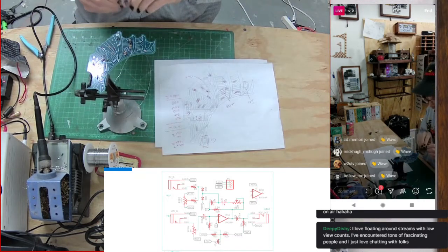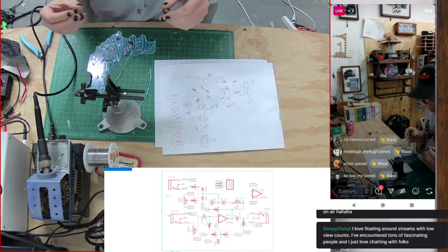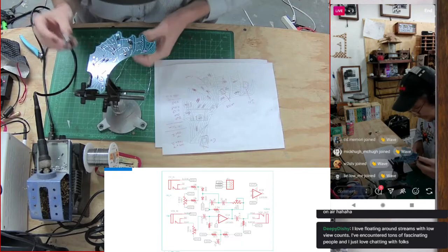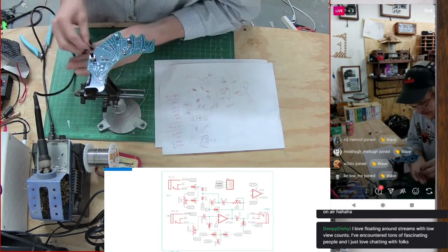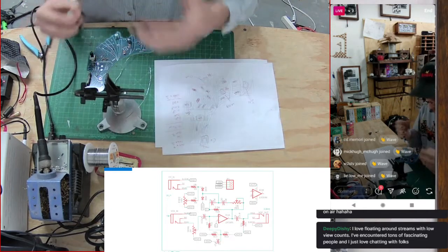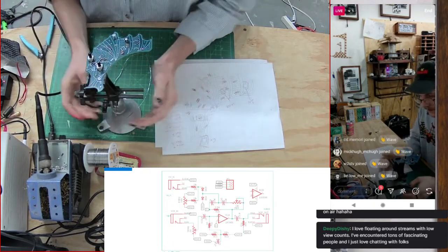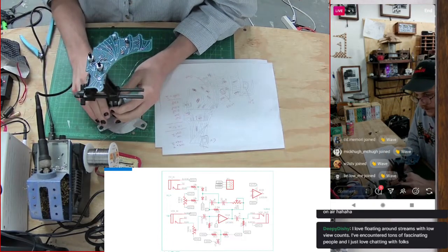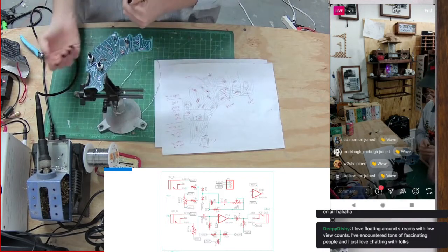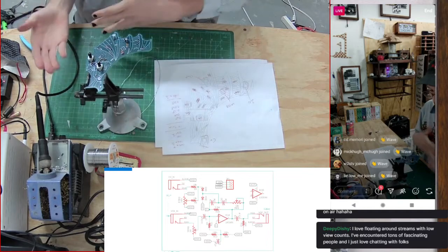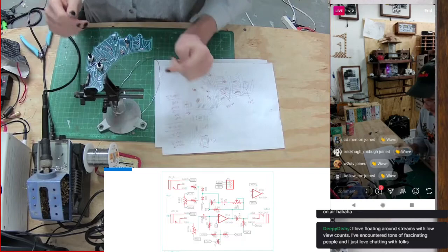So now we're going to put in the regular potentiometers, with a 10K and a 100K. The reason there are 2 is because this filter has an adjustable parameter called resonance. Resonance is a feature of a filter, because in this case our filter uses an operational amplifier, or op-amp, which I talked a little bit about last time, because that's what we used for our oscillating source.